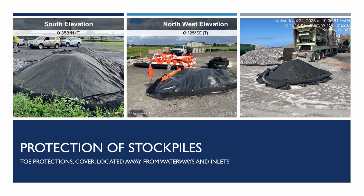Soil stockpiles must be covered with impermeable measures or stabilized and have toe protections implemented around the entire toe of the stockpile. Stockpiles must be stored at a minimum of 50 feet or as far as practical from waterways and inlets. Contaminated soil stockpiles must be stored on an impermeable liner or device, surrounded by an impermeable berm, and covered with impermeable measures.